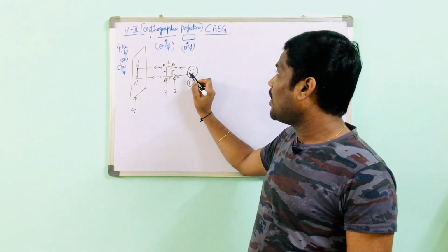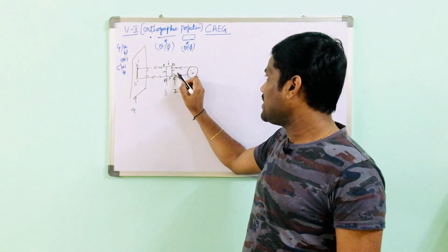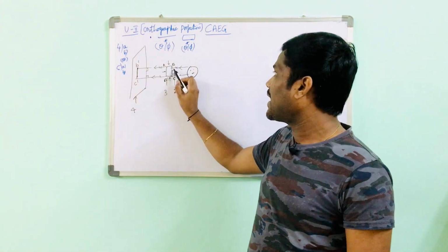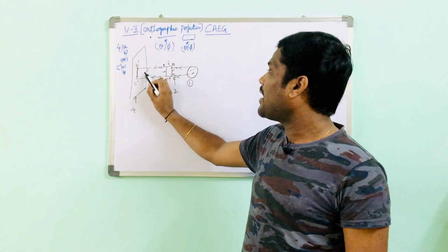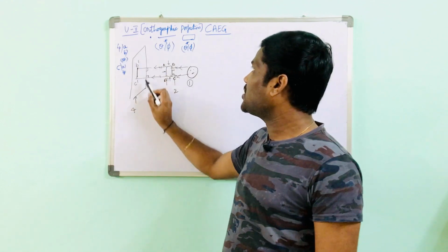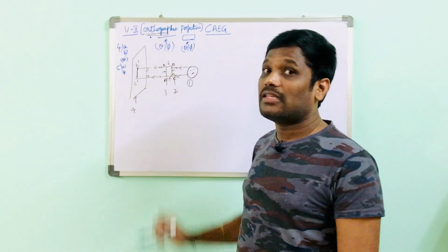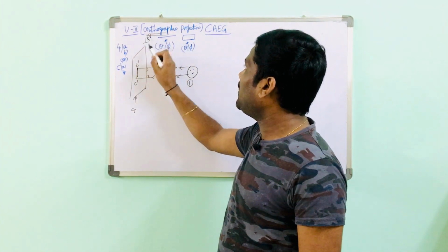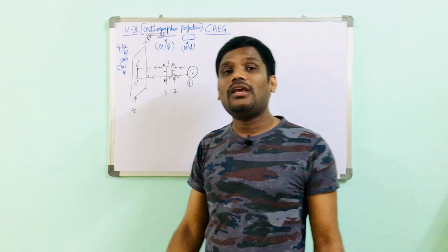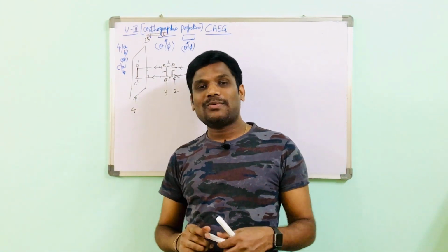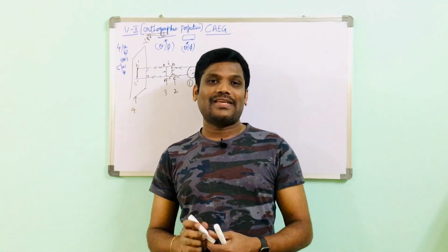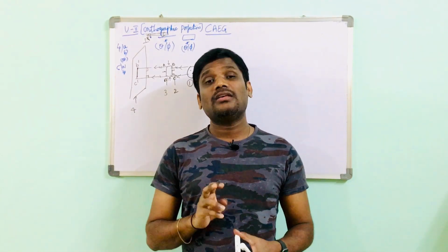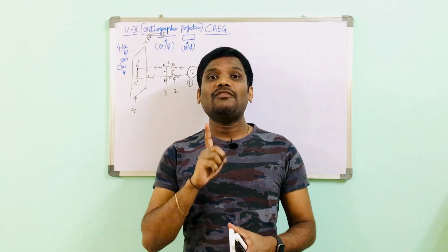So why is it called a parallel projection? If you see, the rays passing from the source are parallel to each other and perpendicular to the object as well as perpendicular to the plane of projection. Such a type of projection is orthographic projection. I told you it is a 90 degree or perpendicular projection, and graphic means the drawing. This is a point you are supposed to write in the exam if they ask you to define orthographic projection, dear students. And it is also said to be a multi-view projection.